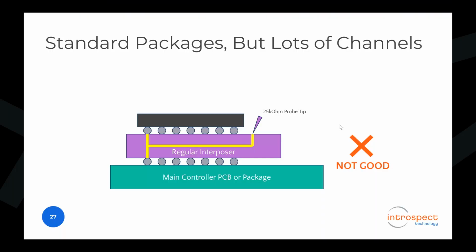And so last, of course, is the interposer itself, right? Because this is the big part of the puzzle. And this is something, again, that we have studied for a long time at Introspect. And we have looked at conventional interposers with the LPDDR and DDR applications. The thing about these applications is this: they are standard packages for sure, which is good. So it means you can buy interposers from third-party vendors, or you can create standard interposers. But the large number of channels makes it very, very unwieldy sometimes.